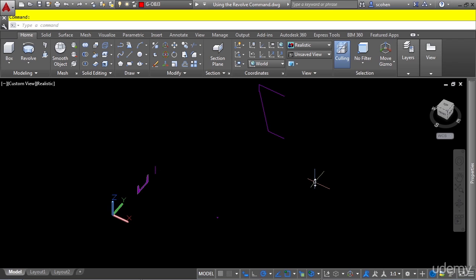Now, for some models that show material that is bent, rolled, or cast in an arc or circular shape, revolving a profile is the only way to achieve the needed results. In other cases, it will just be a lot faster to draw a profile and revolve it than to create and combine solid primitives. You'll be more productive and successful in revolving profiles if you know how to use the revolve command and its options to control the model's creation.